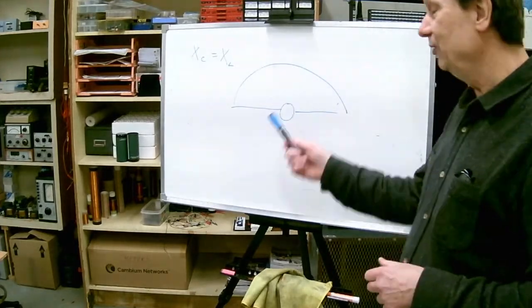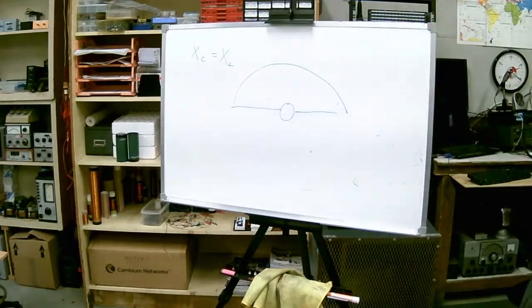Looks like an antenna is too short. The impedance would be higher. Well, let's see, which direction? Are you asking for the radiation pattern? Not the radiation pattern, no, just the impedance. What's the impedance look like for an antenna that's too short?